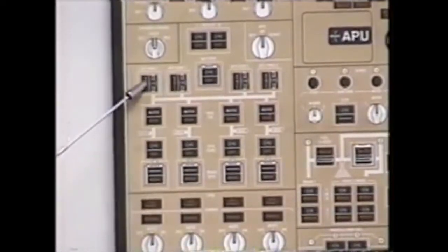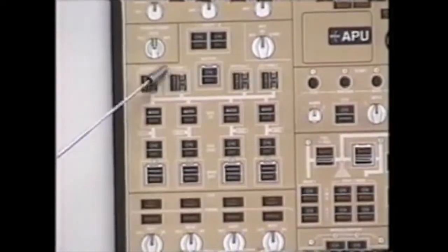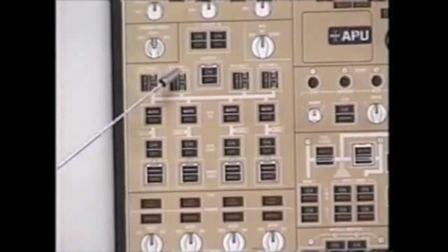External power needs to be plugged in. It does not need to be on. If you place external power on, it will still power the ground handling bus. If external power number 1 is not available, start your APU. As soon as the avail light comes on, the ground handling bus will be powered. You can place the generator online, powering your airplane. It will still power the ground handling bus.